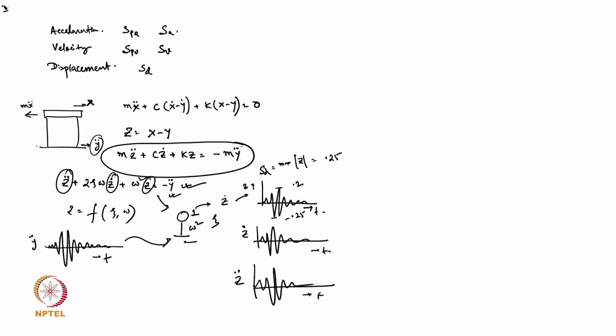So what is SD representing in this equation? We have these two equations, maybe equation number 1 and equation number 2. What is represented by them? It means the maximum of Z. Or if you think of it from the physical point of view, that is the maximum displacement of the story, or the maximum displacement of that single degree of freedom system with respect to the ground.